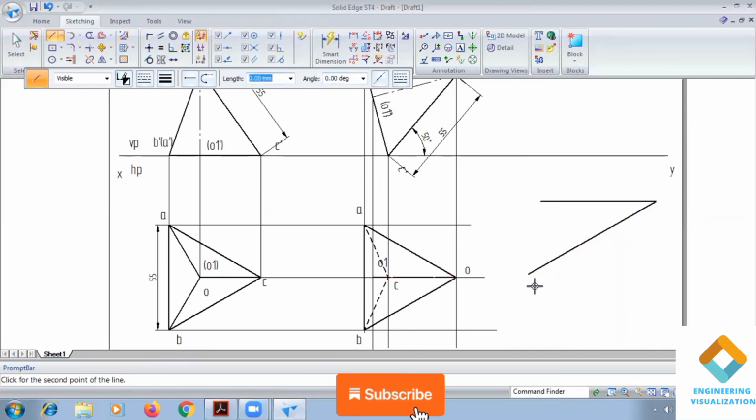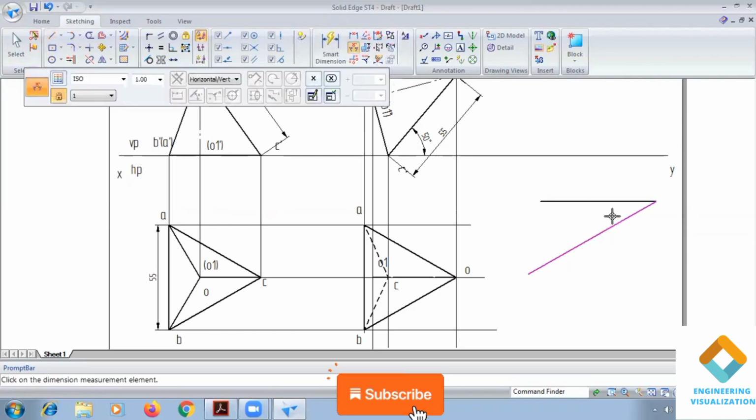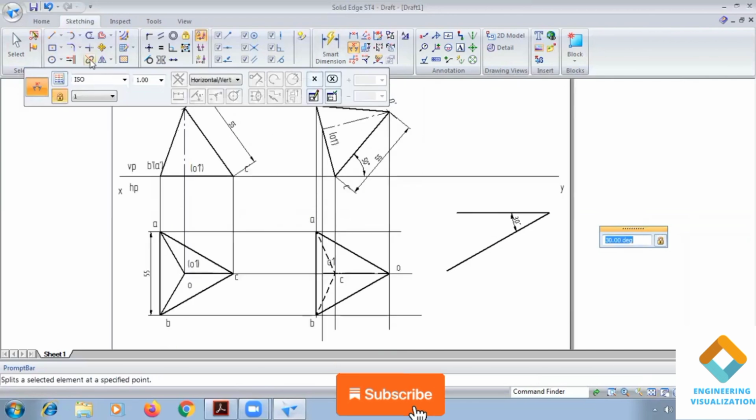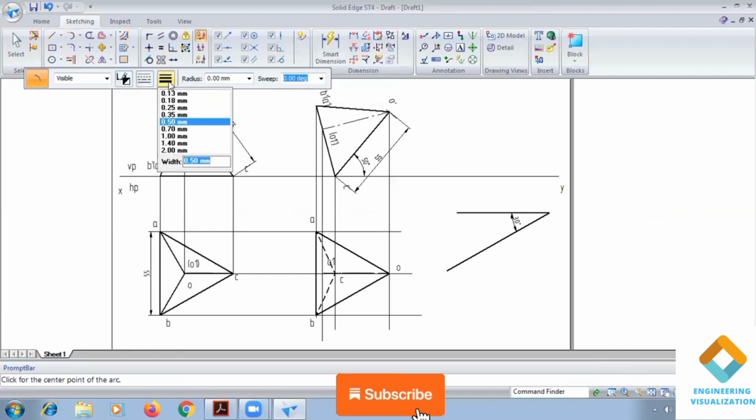Okay, angle 30 degree. So minus 150 if you give, it will take 30 degree. Now here the slant edge length you need to use, that is 55 mm. So go to arc by center. So take 55 mm length and cut the arc. Okay, now draw the locus line.